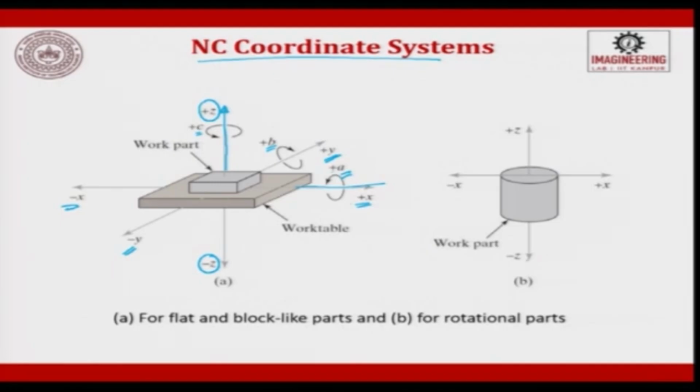When you go for a cylindrical job, you will not have a y axis because diametrically it is the same. So, the y axis overlaps with the x axis. You will have the x axis and z axis only. So, for a lathe component you will have x and z axes only. The z axis becomes the spindle axis and the x axis becomes the diametrical, you give a depth of cut, right. And then plus and minus is when you move along the direction of the workpiece. So, when you talk about prismatic, we will have x, y and z.